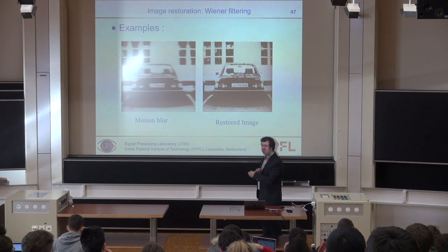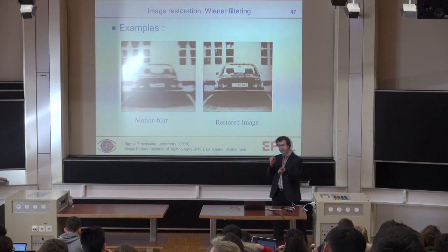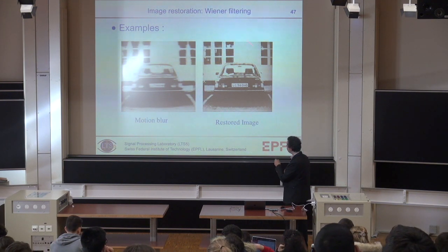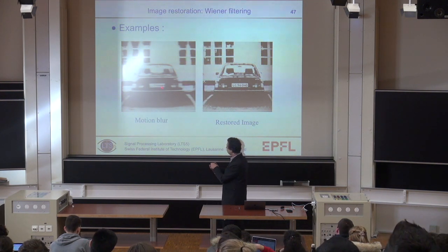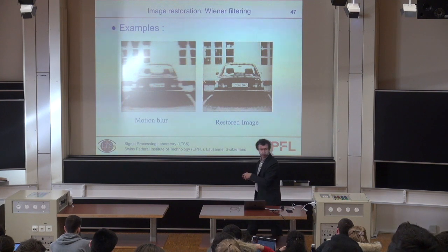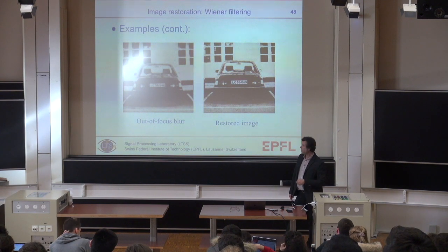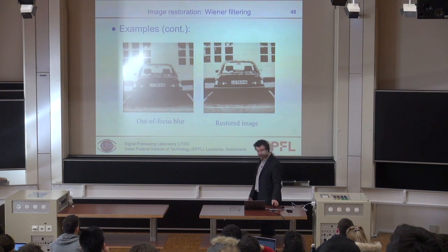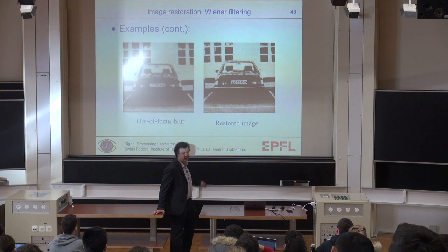If that image was not blurry, I would do a high-pass filter. It is blurry, so I do a Wiener filter, which will basically estimate if it has to restore or not. And you get that. This is probably a motion blur, so it's horizontally blurred, not vertically, as you can see. And this is for a real blurred image, and you get it back. And you see that it looks a bit noisy, but see where we come from. Now, just to finish, and then I'm done, estimating the impulse response is not that difficult on this.